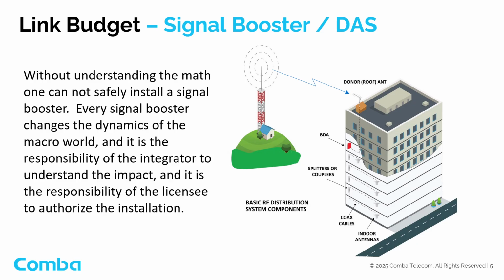appropriate gain and power levels needed to achieve the required coverage without causing interference to the outdoor macro network or designated radio site. The system integrator or BDA operator is required to provide an RF link budget showing the BDA system will work as intended, with margin for adjustments during the installation and commissioning.